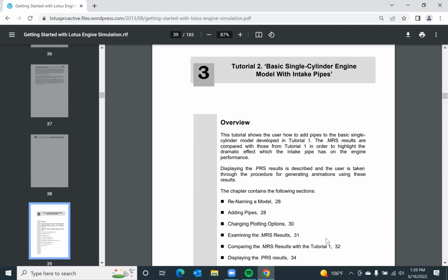But the exercise that we do is very important because that gives you a starting point. Right now, you don't know, for a 25 kilowatt, 3000 RPM engine, should I use an 80 millimeter bore, a 100 millimeter bore? What would be the cylinder dimension? Our hand calculations give us the starting point, and then these computer simulations help us refine those dimensions.